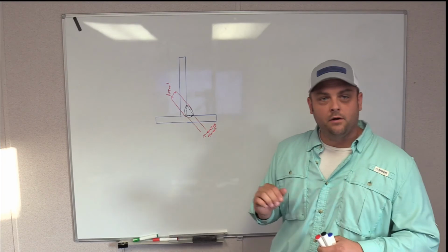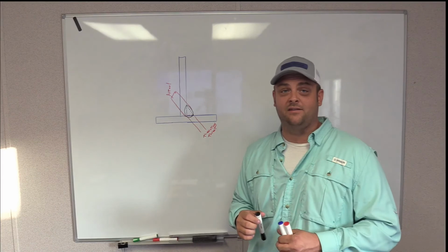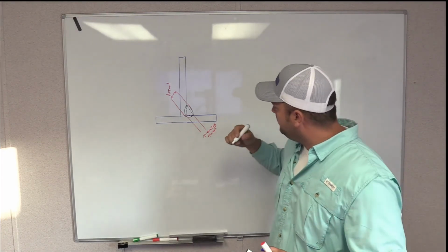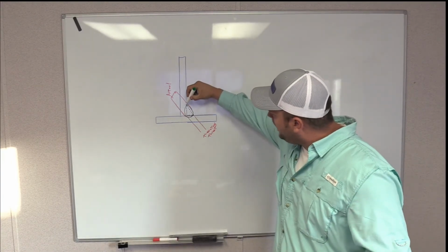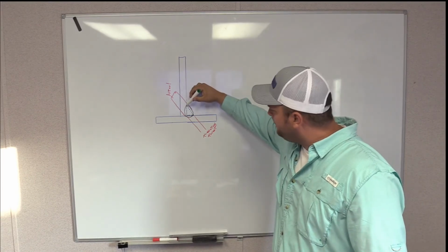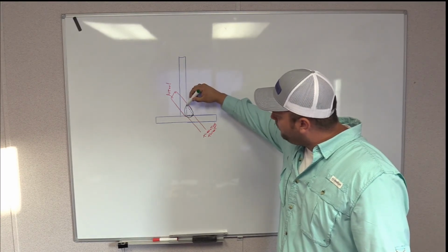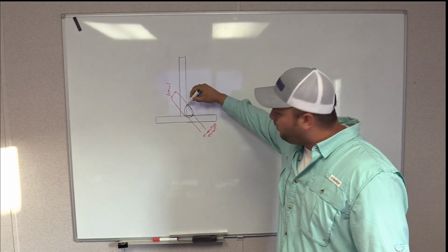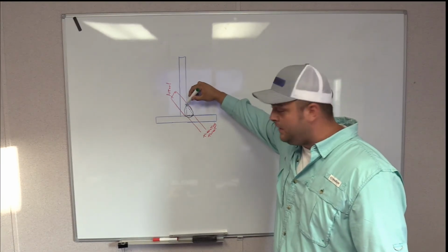Now, the third throat that you have to be aware of is called the effective throat. The effective throat comes from this point right here, as if it was straight across. So you take where your maximum convexity is, and right where it starts to become convex and meets the parent material, at those points right there, that's where the effective throat begins.